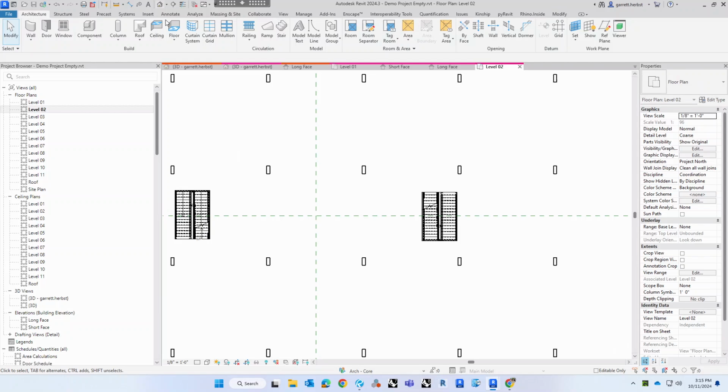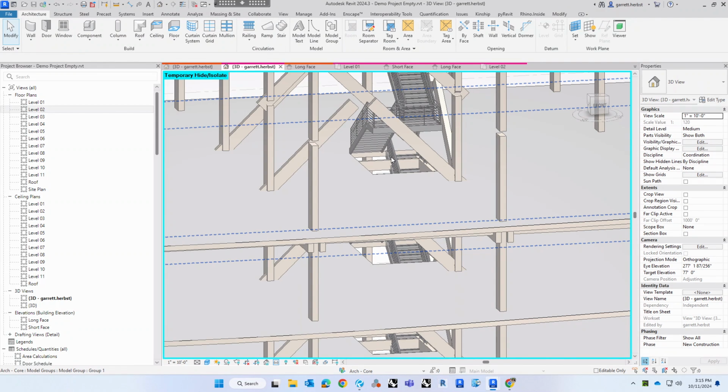So your beams, your purlins are all going to respond to that and be oriented around them. That's one thing that's really big in any sort of shaft condition, especially with stairs: making sure that your stairs do not come up to a landing and then there's a beam on top, because then people will smack their heads and you'll get sued.